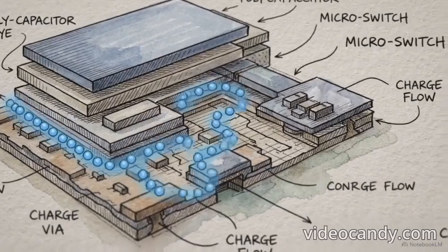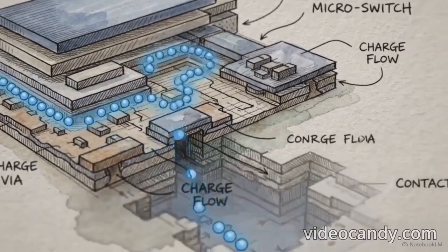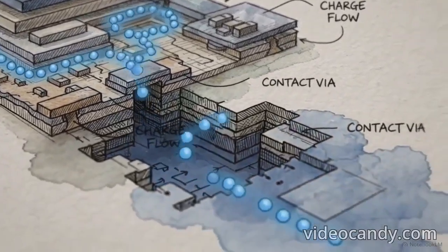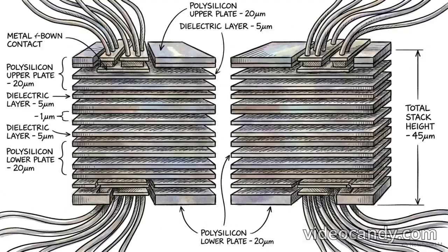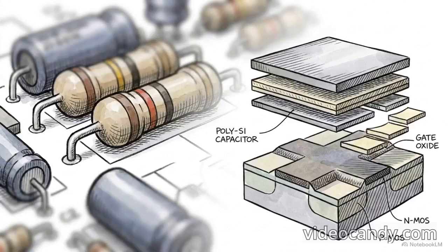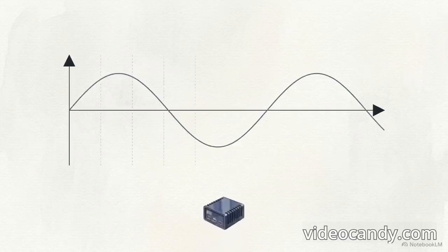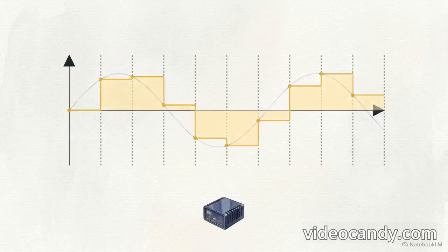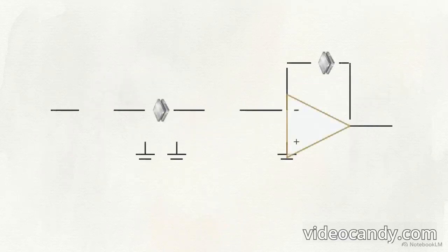The industry solution was to stop using physical resistors entirely. Instead, engineers replaced them with capacitors and a network of precisely timed switches. In semiconductor manufacturing, capacitors can be fabricated with highly accurate relative sizing, meaning their ratios match beautifully on the die. To save area and guarantee mathematical precision on modern silicon, designers had to let go of continuous flowing currents. Instead, the architecture moves to a discrete time system, trapping and transferring tiny, exact packets of charge.